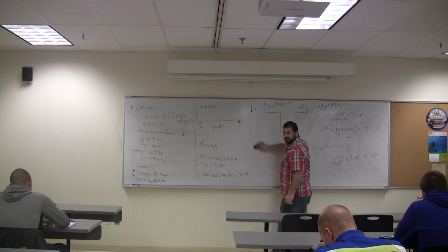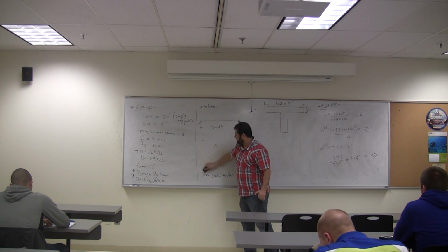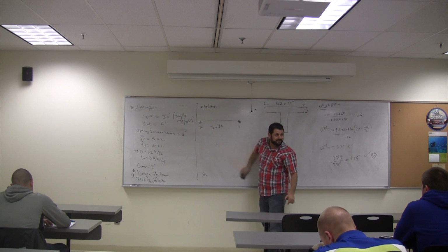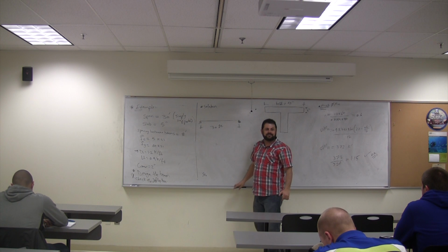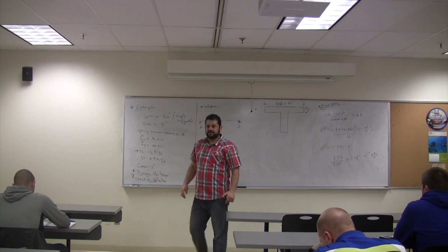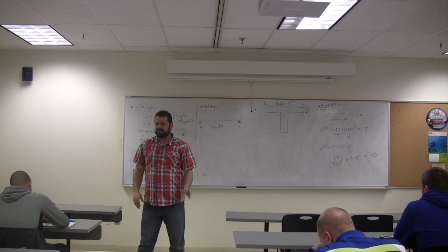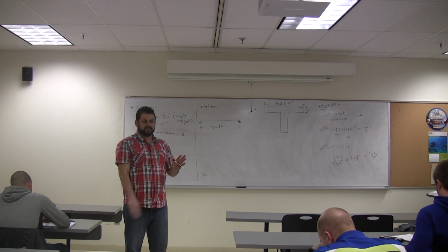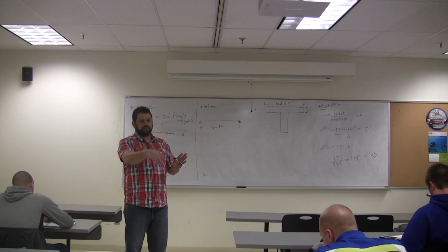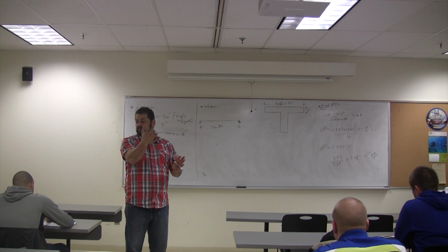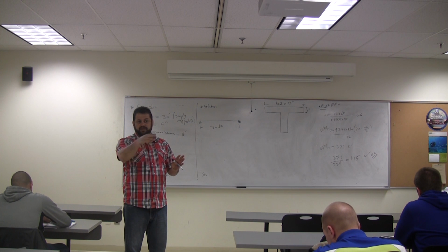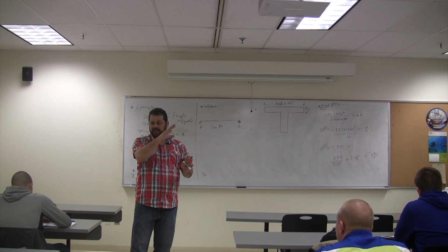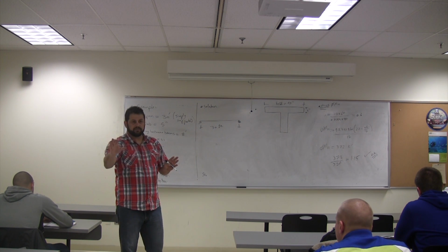Can you design this for shear? You should. Just draw the shear diagram. It's linear. Find the value at the critical section. Calculate Vc. See how much Vs is needed at the critical section. Design the stirrups, the spacing right there. Then find the 3 regions: the region where the maximum spacing is needed, and the maximum spacing has 4 equations, and the region where no stirrups are needed, which is when we have V ultimate less or equal to phi Vc over 2. 3 regions.